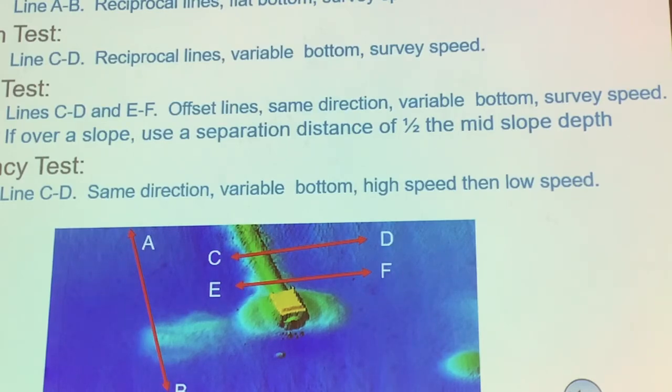You have to redo again, which is sometimes a lot of waste of time, because for example, every time you take out the multi-beam and then the next day you do survey, you must do patch test again. So sometimes for some patch tests, it can take 1 hour to find a good area. So you want to reduce the amount of time that you do. So when you have the chance, do a nice big patch test. That way you have some extra space to go and work around.